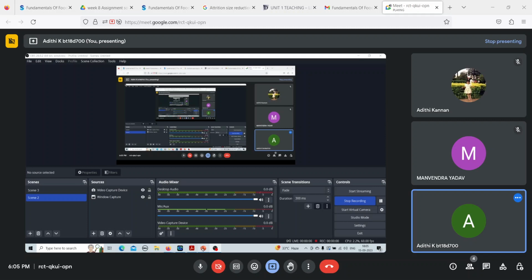When we say fraction retained, it means 12 divided by 110 is what is retained in the pan. 34 divided by 110 is what is retained in sieve number 15. 36 by 110 is retained in sieve number 30. 18 by 110 is retained in sieve number 50. 10 by 110 is retained in sieve number 100. So this is the fraction of weight retained.